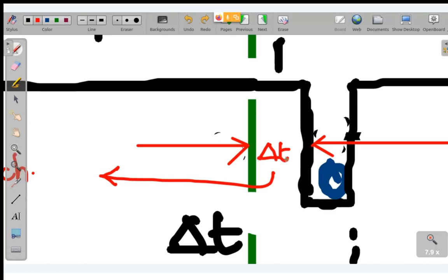See, glitch is only for del t time. Glitch is happening for del t time, but you can look over here that at this clock pulse our flip flop changed its state from 101 to 000.